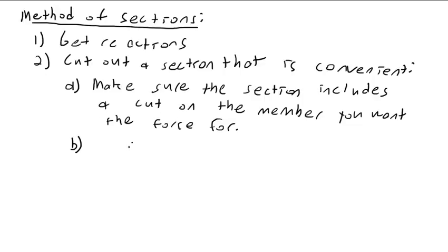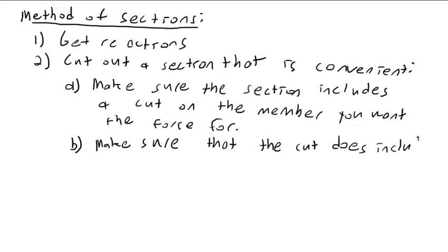So yeah, make sure the section includes a cut on the member you want the force for. Make sure that the cut does not include more than 3 unknowns, because that's all we'll be able to solve for.